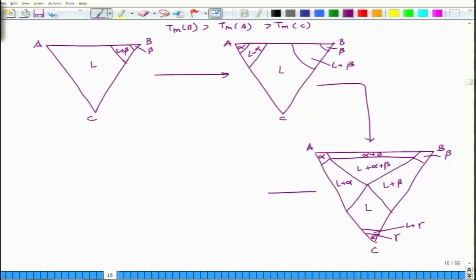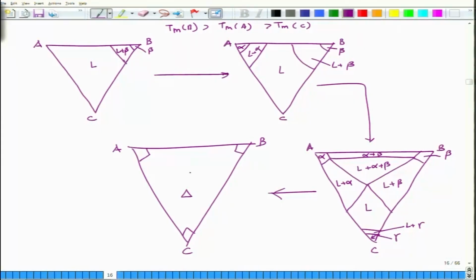Now if you further decrease the temperature, you might encounter at some point something like this. It's not a very equilateral triangle, but nevertheless, for the sake of representation, you might encounter something like this. So you have a beta phase field, you have a gamma phase field, and in between you will have some tiny liquid phase field here. This liquid phase field is connected somewhere here.